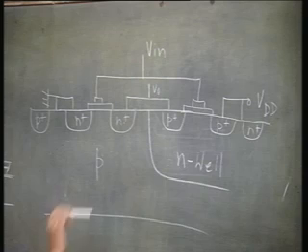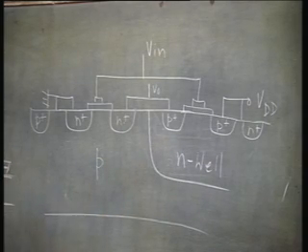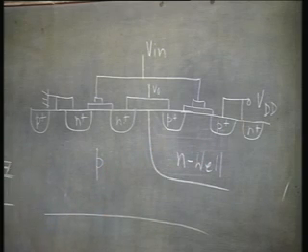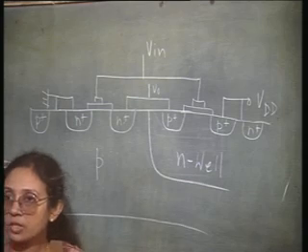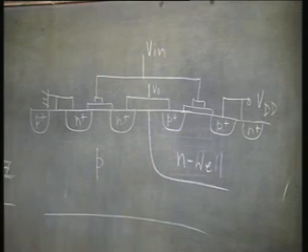If there is sufficient resistance in this Nwell, remember your well doping concentration is pretty low, there could be a potential drop as the current is flowing. It could so happen that this potential drop is sufficient to turn on this PN junction as well.